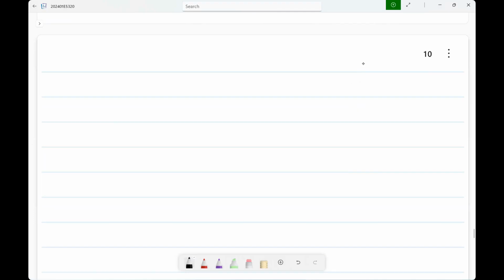And for analog, it sort of makes sense. Typically, you bias it such that one side is more positive than the other and then operate like that. So you can distinguish. But the device itself is symmetrical, so it is also useful to have a symmetric model. In fact, the asymmetric model does have some problems because you have to check which is the drain and the source and switch it. Many of the earlier models had all kinds of discontinuities when VDS crossed 0. It should actually be symmetrical. Whatever it is, we may or may not be able to write the expression for it, but clearly it should be symmetrical.